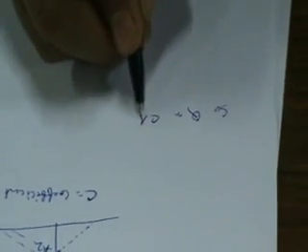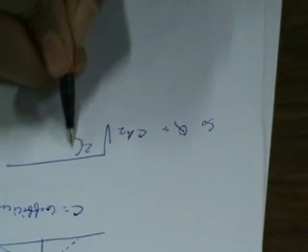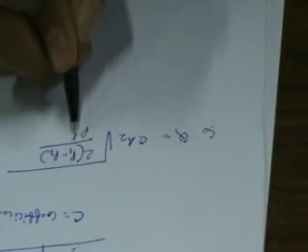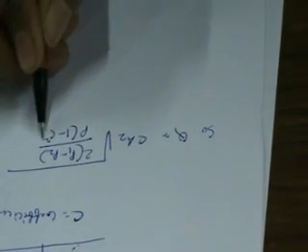So we can plug it into the equation. Your Q will be C A2 square root of 2 (P1 minus P2) by rho times (1 minus C square m square).